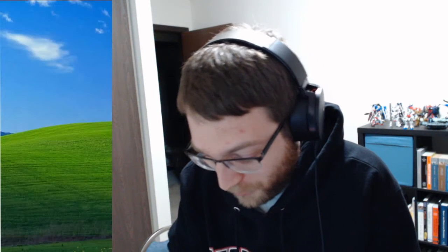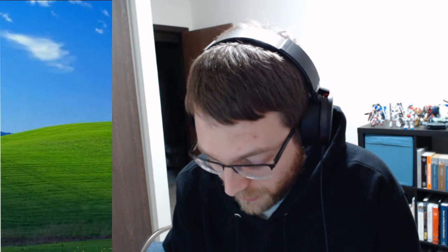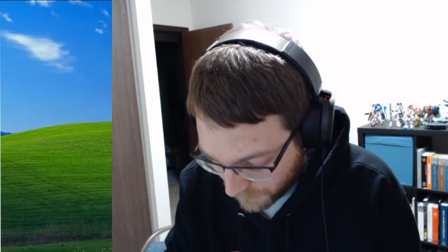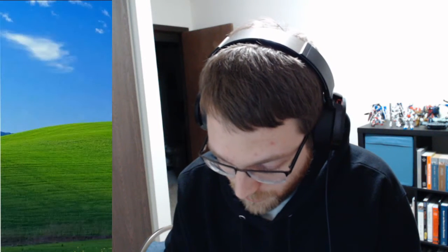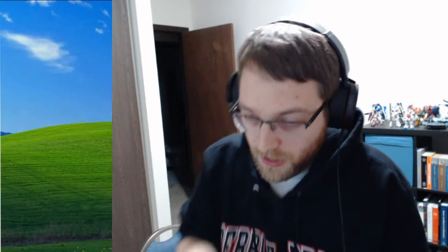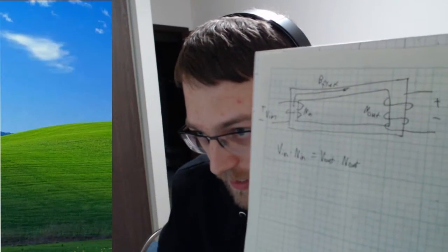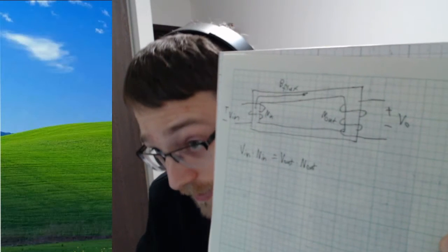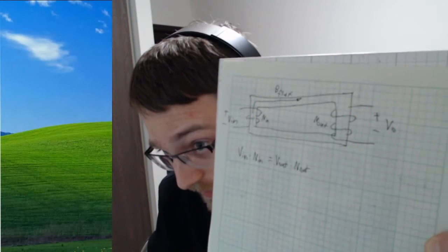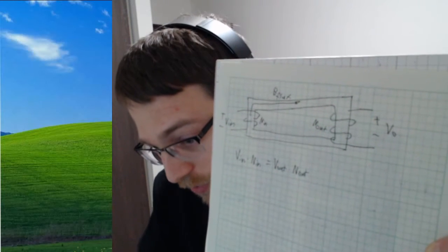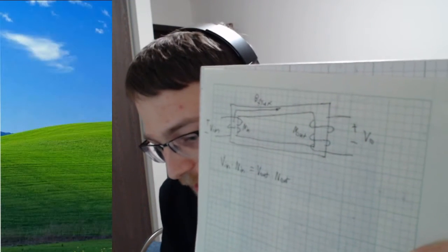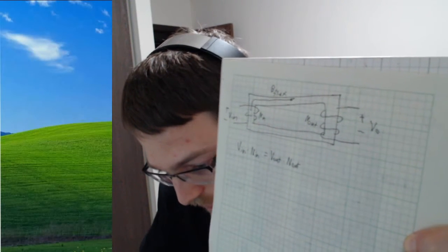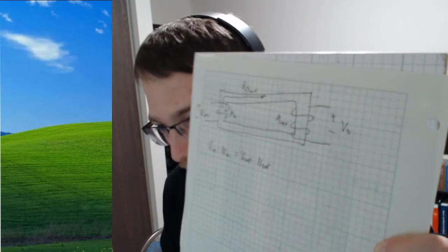But what ends up happening is your input voltage times the number of turns you have on one side is equal to your output voltage times the number of turns you have on the other side. The thing about transformers is since it is always consistent, because it is a passive device, it'll just continually roll through. It won't have that much loss. The other nice thing about this is it's just a straight conversion. The output will follow the input all of the time.